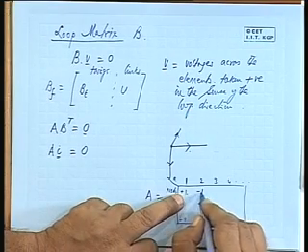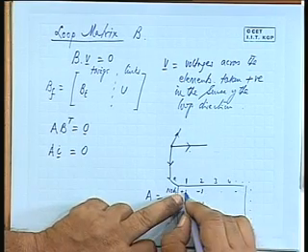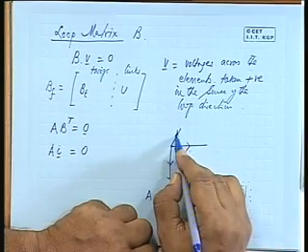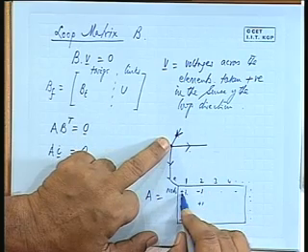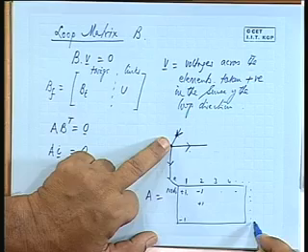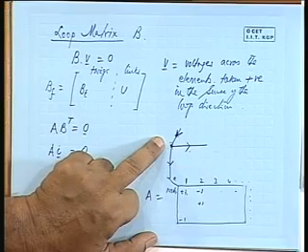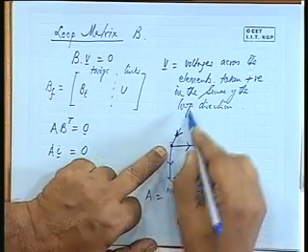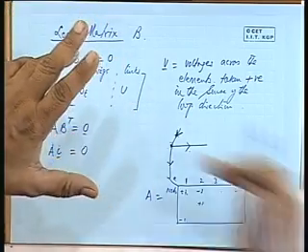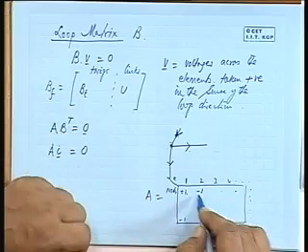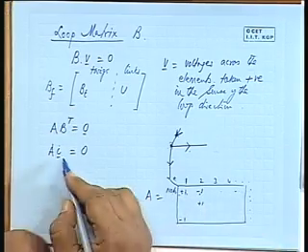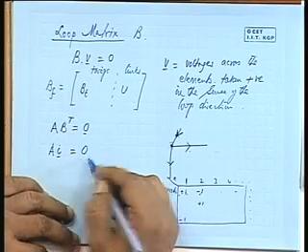If I take the sum of these currents, I1 into plus 1, I2 into minus 1 and so on, the first row multiplied by the current vector will give me 0, that is Kirchhoff's current law. I1 plus I2 plus I3, all the currents going out, if taken as positive, should be equal to 0. If there is a current coming in the opposite direction, it will be negative, and that is reflected in the A matrix. So, basically A into I equal to 0 is our well known Kirchhoff's current law.